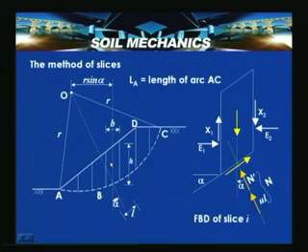So, one alternative available is to divide it into a number of vertical slices. Nowadays, the method of slices is also coming in the horizontal direction, called the horizontal method of slices, but currently we will be discussing only cutting the slope portion vertically.